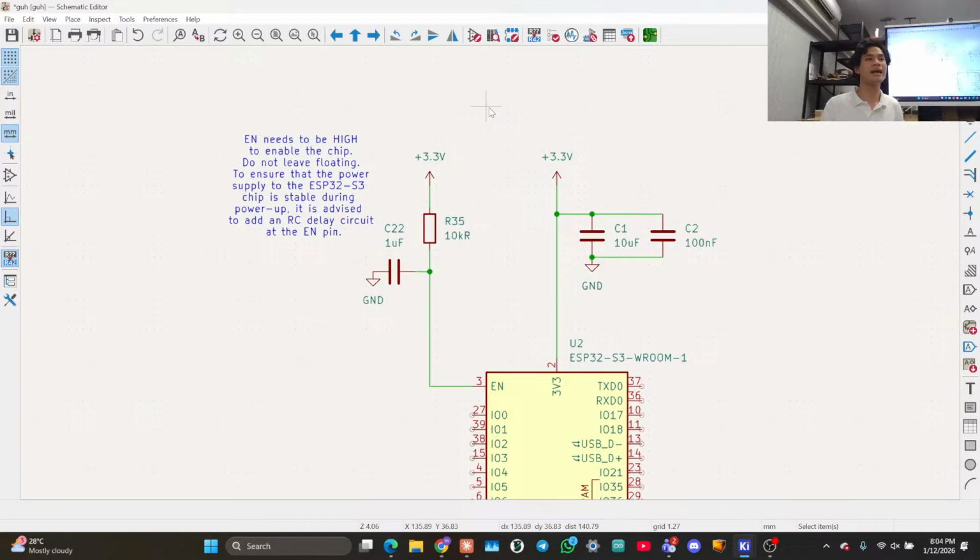By default, we say that ground is 0 volts, and then everything else is like 3.3 volts. This is convenient, because then I can see what the potential difference is, because ground is 0. The difference between 3.3 and 0 is just 3.3, which is my potential difference, right? If I put 100 and 103.3, then the circuit works exactly the same. Nobody cares. There's no difference in the physics. But then now I have to actually subtract things. Isn't that annoying? So negative is just what you define to be the low position.